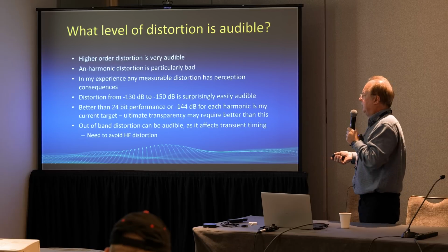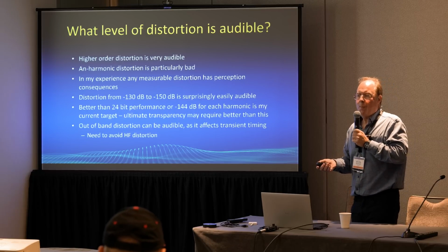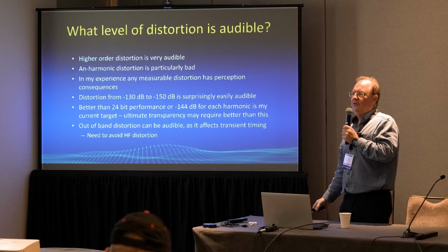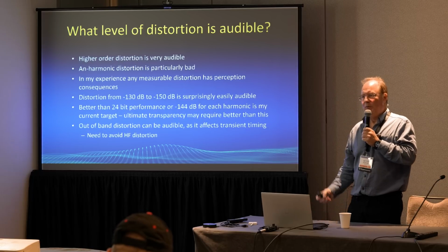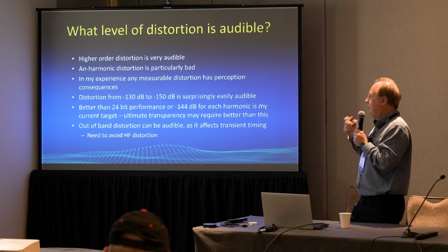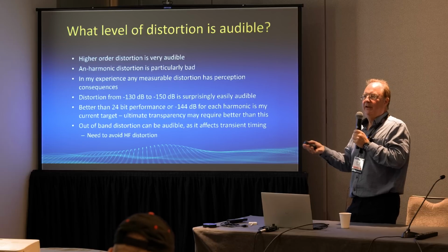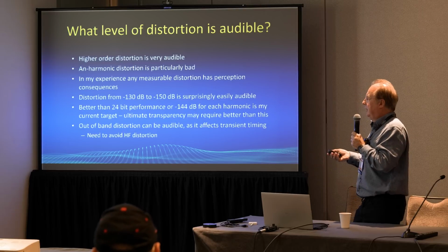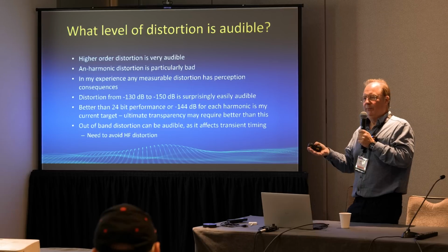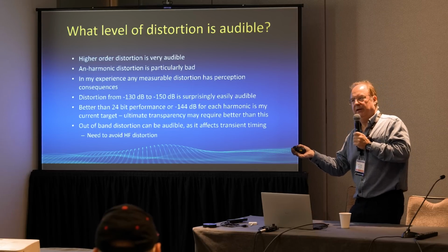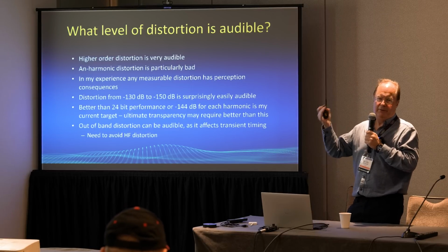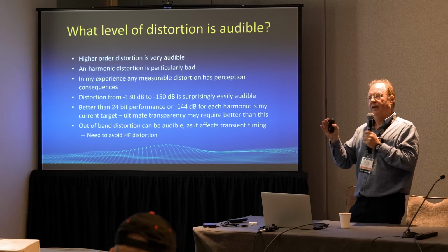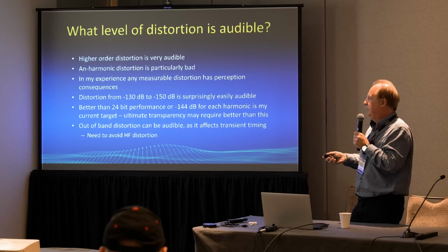Curiously, out-of-band distortion can be very audible. Now, this is pretty weird to think that distortion at 250 kilohertz can have an audible consequence. But one time I had a problem at that level, reduced it, and you could hear the difference in sound quality. The mechanism for that is not that we can hear 250 kilohertz, but the effect of high-frequency distortion changes the timing of transients. And if that happens, then it becomes perceivable.